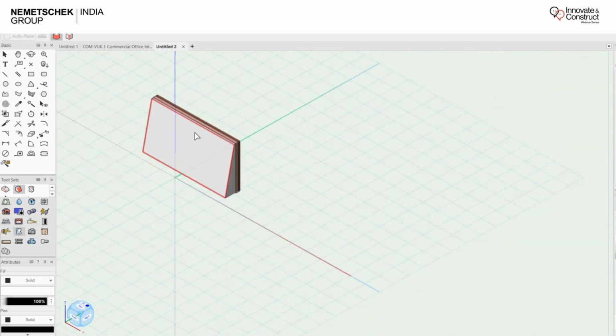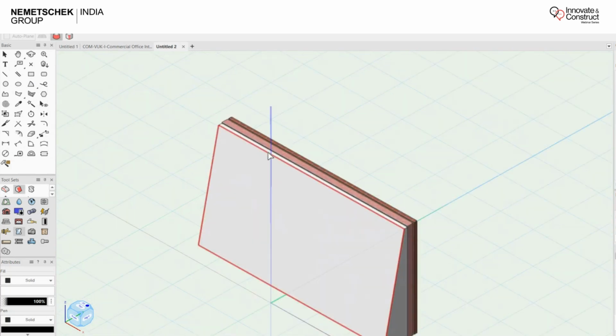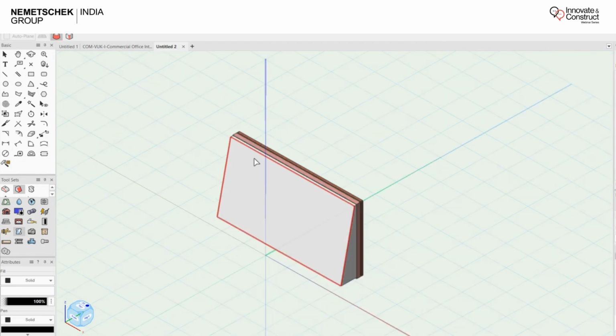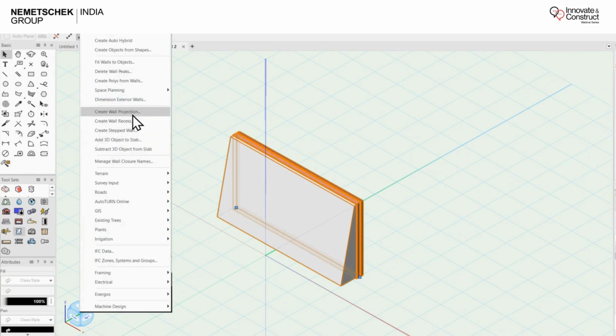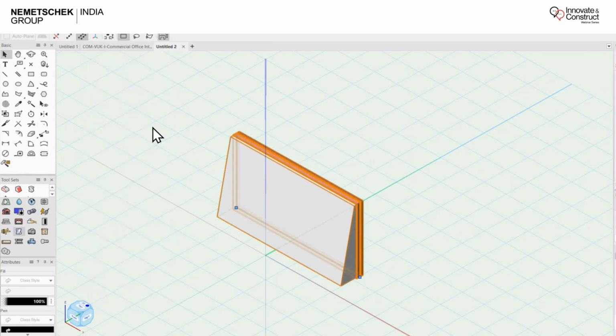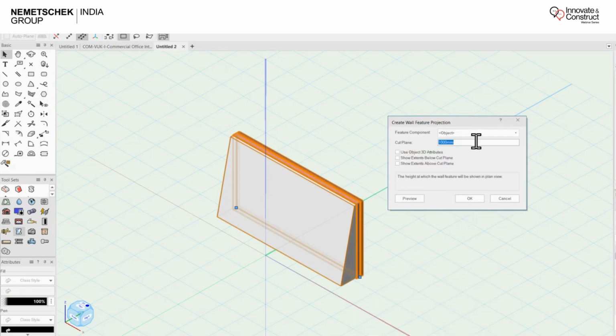Right, if I define this as a tapered wall or kind of a different custom, obviously I can create my custom profile here. I was going to show you the custom profile, but we have a bit of limited time. You can always use your own custom forms here as well. And then I can always select this, go to the ACC and say create projections. When I say create projection, it will read back your projections and define those into the boundary as well. So it will define that into the project.